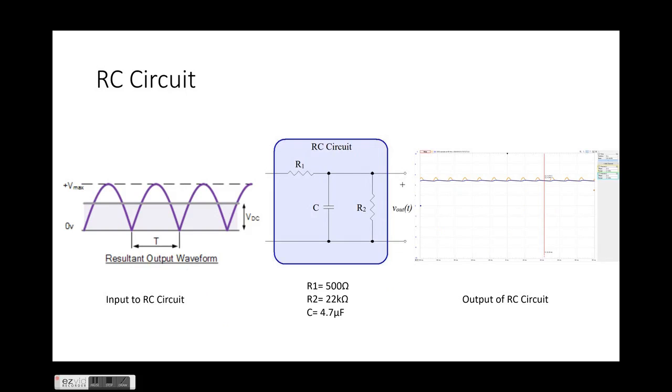Moving on, we now have this fully rectified output, and this is going to go into our RC circuit. A capacitor is going to charge and produce an output, which you see on the right side. Basically, we've taken originally a sinusoidal source, rectified it to give us all positive values, and then put it through an RC circuit, which results in essentially a DC positive source, which is a very powerful tool for electronics.